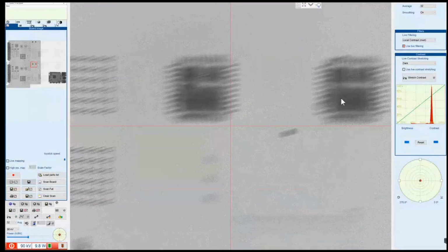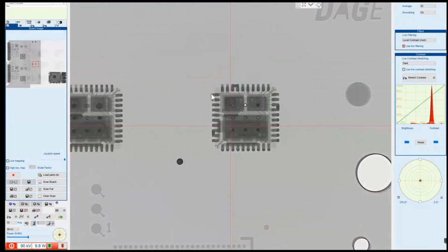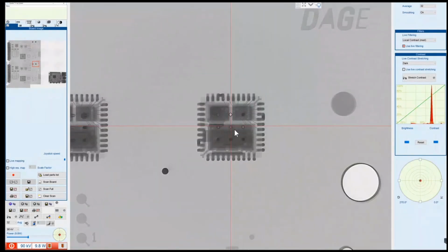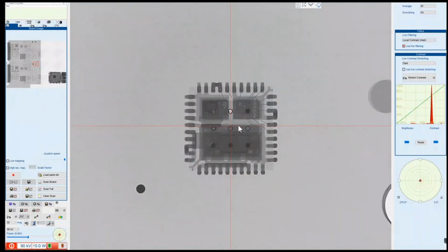Now, if I want to run an X-plane scan on this QFN device here, you can see to the left of this QFN, there's a little ball that's been placed. Now, this ball is generally used for remote fiducial scans. But because today I want to focus on the advanced features, someone who's at the advanced level of X-plane should be able to do a local fiducial scan on this QFN. So that's what I want to show you today. So I'm going to start by zooming in.